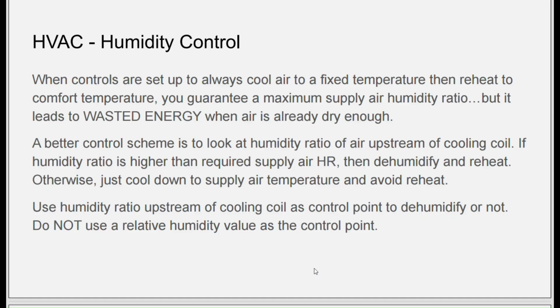So when your controls are set up that way that I described, it leads to energy waste. It's a little bit dramatic, but it's true. It is wasted energy when the air is already dry enough. So like I said, the better control scheme is to look at your air starting conditions versus your final conditions and say, okay, is my dehumidification needed? If not, then just cool it down to the supply air temperature directly. Don't overcool it and then reheat it. We sometimes call that flip-flop control, where you flip and flop between dehumidification mode or just cooling mode.